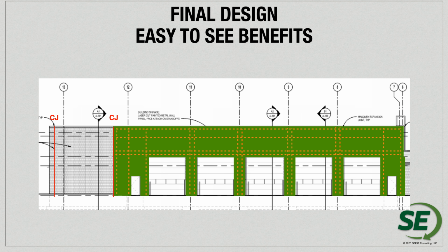So recognizing potential reinforcement that we would have within this elevation, say we have masonry lintels over these doors. We're a strong advocate for masonry lintels within masonry walls. So you have horizontal reinforcement in those lintels that we can make continuous. We have a roof support bond beam that's going to be a continuous reinforcement. And then we're also going to have a top of wall reinforcement that can be continuous. So, with all of that reinforcement and the potential for joint reinforcement, we have more than enough horizontal reinforcement so that we don't need control joints in that part of the elevation.